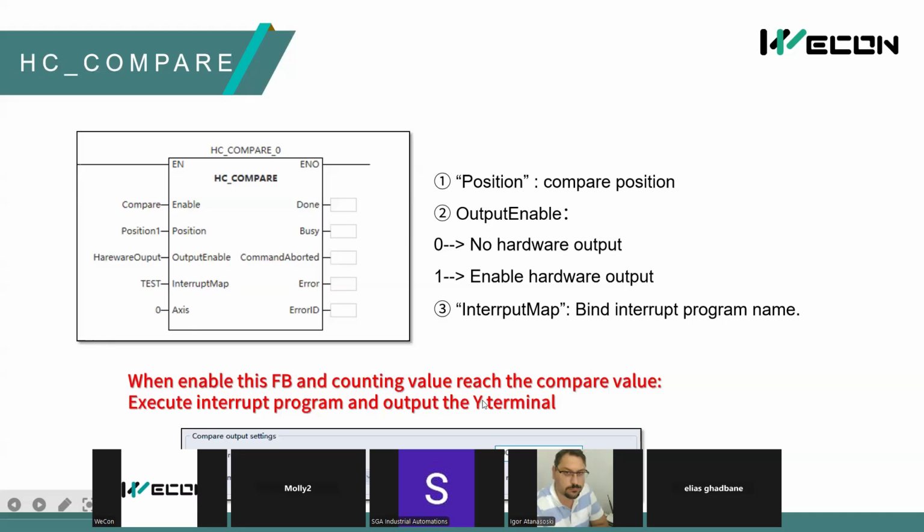And for the output signal of the Y terminal, we have two ways to output it. We can set it as time. For example, it means the Y terminal Y0 will turn on for 1 second when the counting value achieves the compare value.